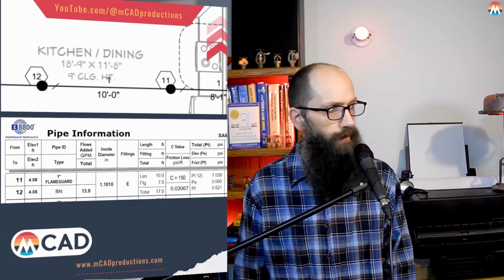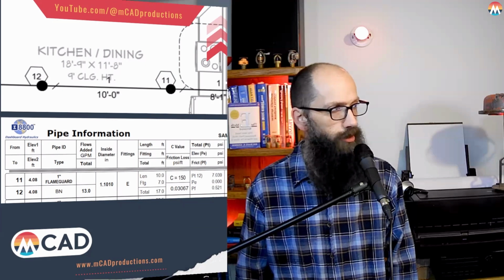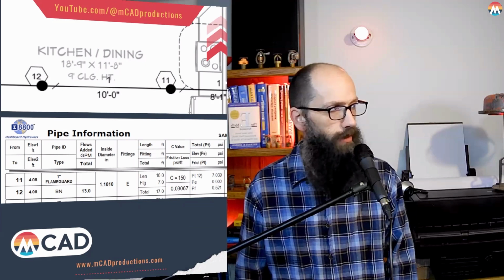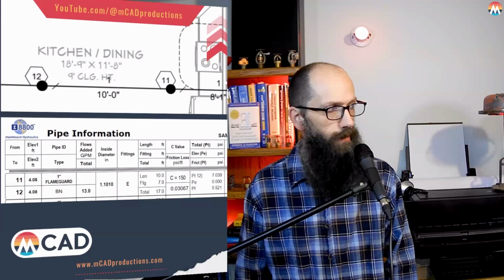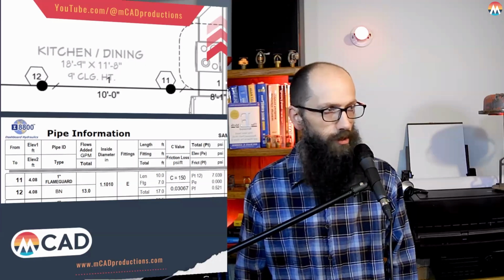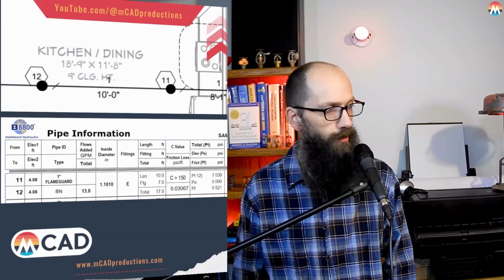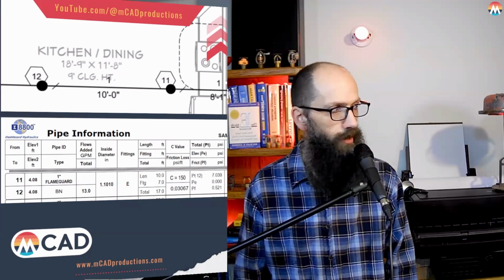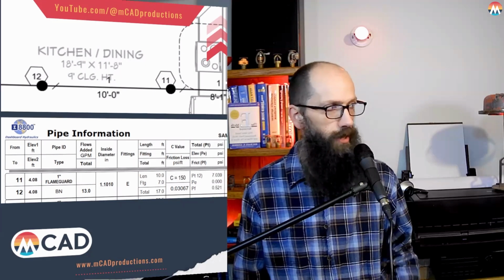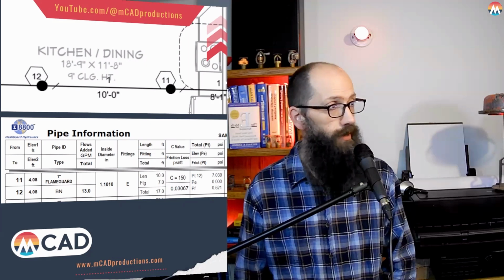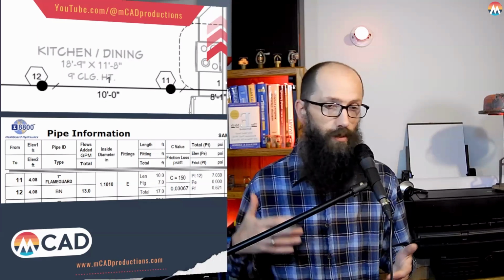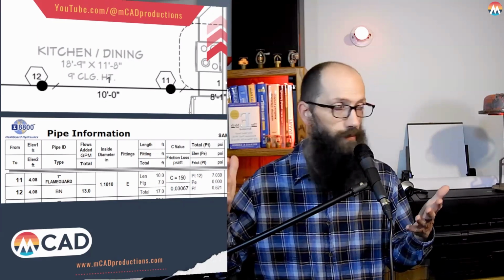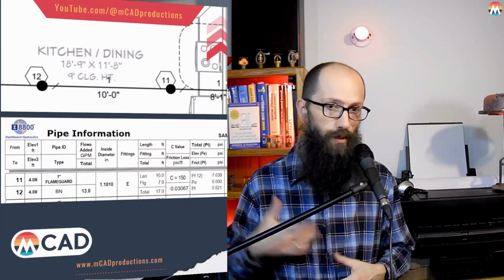Here we have total pressure, elevation, pressure loss, and then friction. These things are all added up here on the side. There's no elevation change here, which is correct, even though they are only at 4 feet. So there's no elevation loss. Our biggest pressure losses come from elevation loss. But basically, in the prescriptive method, you'd be adding up all the fittings to get these same kinds of numbers off of the charts.